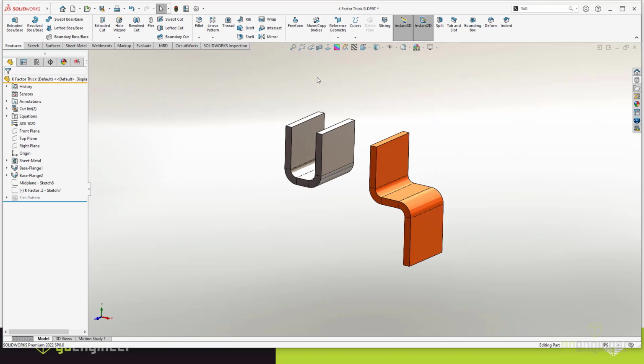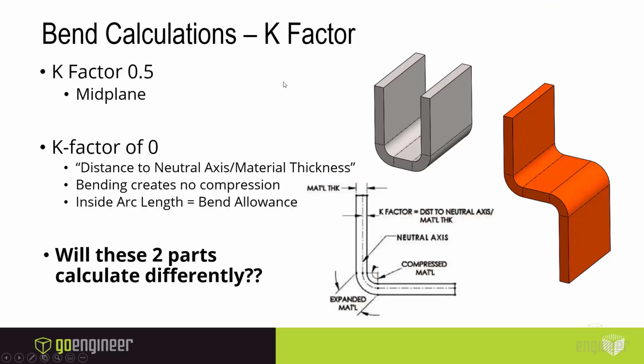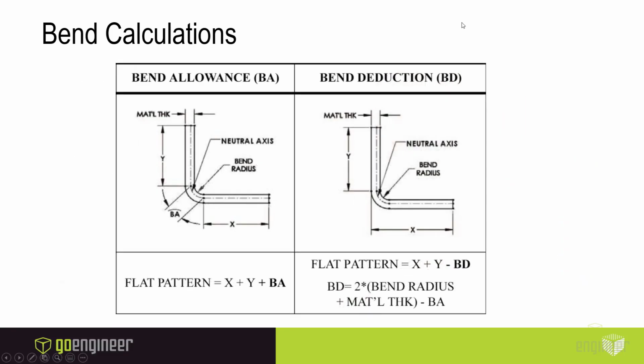So when you set your K-factors, the basics again, once again, is that if you go ahead and start unfolding your part, it will change that length relative to the folded version of it. But it's all based, again, on processing equipment. So a little trial and error will go ahead and nail that to get the accuracy of your processing.